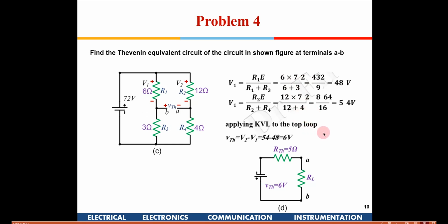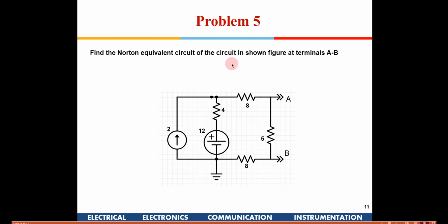Okay, till now we have taken some problems on Thevenin. So let's take an example of a Norton equivalent. We need to find out what the Norton equivalent is. What will be the Norton resistance? Can anybody, just seeing the circuit, tell? This will be open circuit, this will be short, so this will become 8 plus 8 plus 4, right?